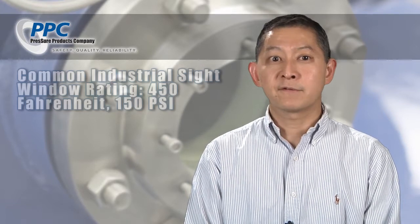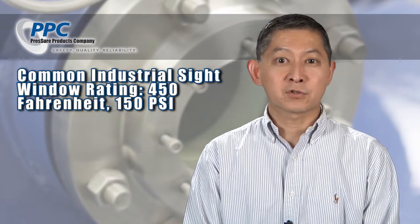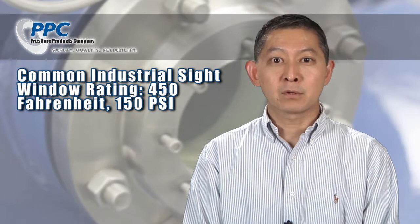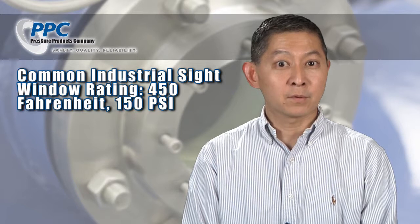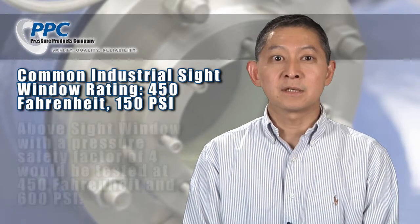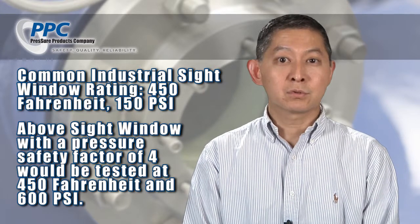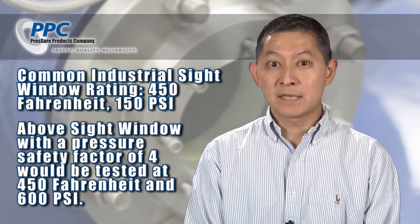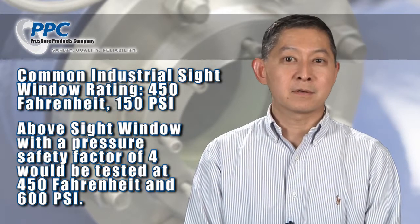A lot of commercially available sight glasses are rated for 450 Fahrenheit at 150 psi. Side windows' pressure safety margins are rated and tested at their maximum service temperature. So a side window rated for 450 Fahrenheit and 150 psi with a pressure safety factor of 4 would be tested at 450 Fahrenheit at 600 psi. The usual rule is that at the max pressure, 600 psi, the side window may leak, but it must not burst. Now that sounds good until you think about it a little.